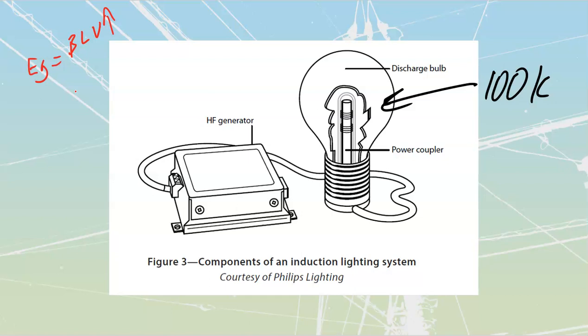Try to keep those ballasts, and obviously this cord, because this cord is going to be carrying that high frequency, as short as possible and away from anything that's telecommunications. Applications: these are all going to be for up-high lighting where we need bright light and lots of it. They give us roadways, airports, lobbies, security lighting, high bays, things like that. They're always going to be up-high ones, nothing down low. They're too expensive to place down near the general public because of the proprietariness of the bulbs and components. You just can't afford to have these things in any place where they're in danger or could get smashed.